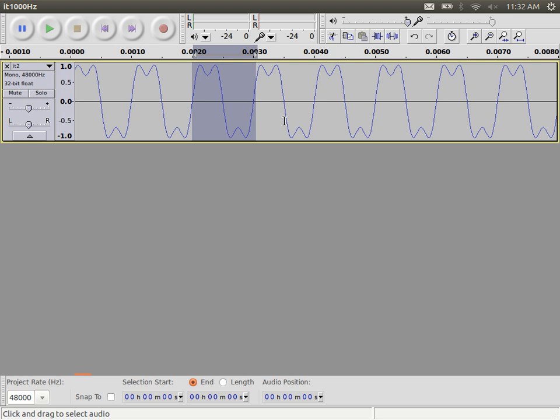Therefore, we can transmit how many bits? 500, 1,000, 2,000, anyone else? 4,000 bits per second. Two bits in half a millisecond. 4 bits in 1 millisecond. 1,000 milliseconds in a second, therefore 4,000 bits in 1 second.